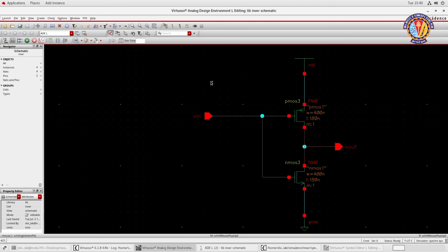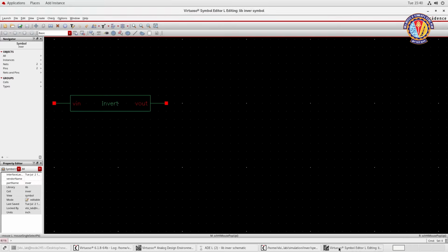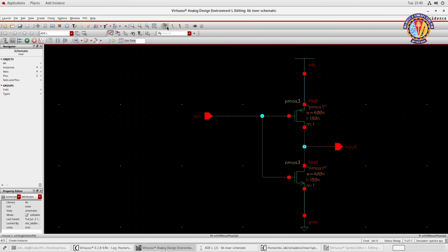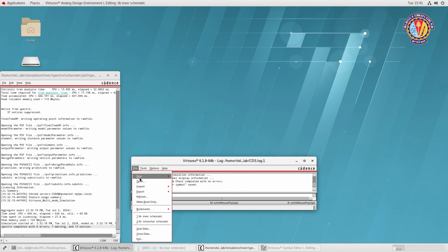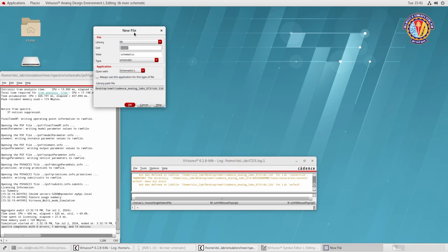See, the usage of symbol is so easy that here we have a transistor, right? So this transistor can be used in any schematics. Similarly, this entire symbol will now appear in your instance column. You can check that. We'll go to new cell view. This cell view is just for placing the symbol which we have created. Okay.